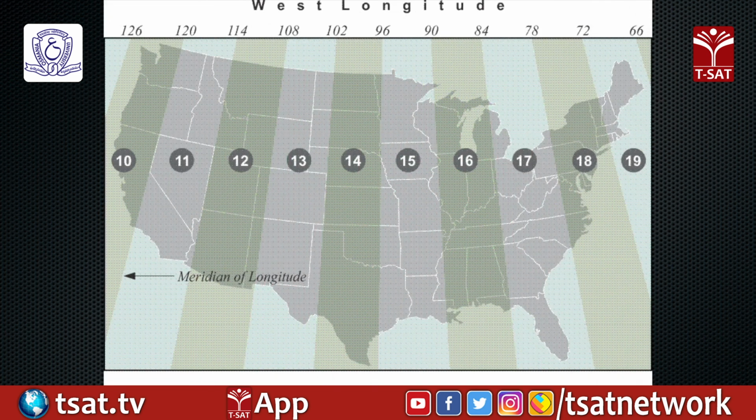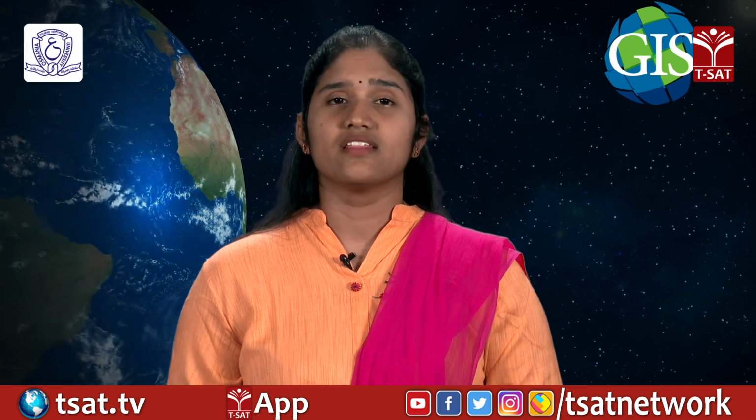For example, UTM zone 10 north refers to the zone between 126° west and 120° west in the northern hemisphere. Each UTM zone is mapped onto a second class transverse Mercator projection with a scale factor of 0.9996 at the central meridian and the equator as the latitude of origin. The use of the projection for the UTM zone is designed to maintain an accuracy of at least one part in 2500. Measuring 2500 meters in the UTM grid system would be accurate within a meter of the true measure.